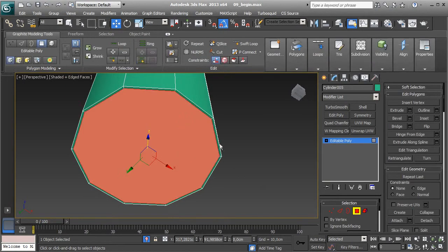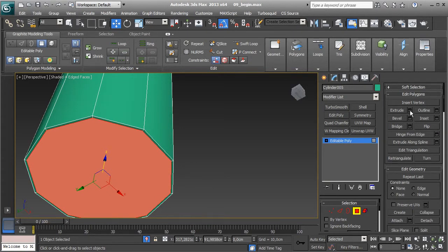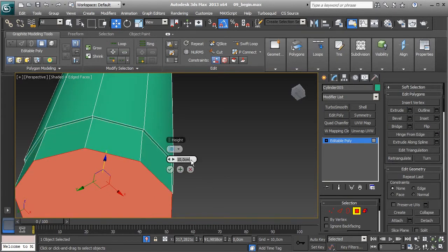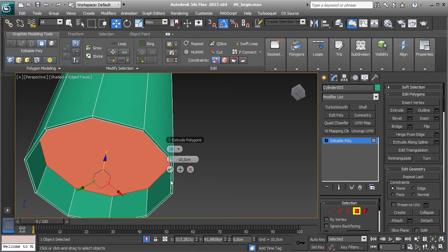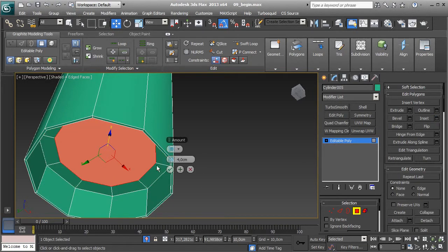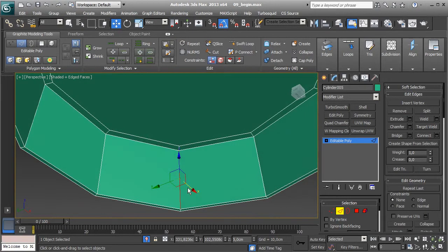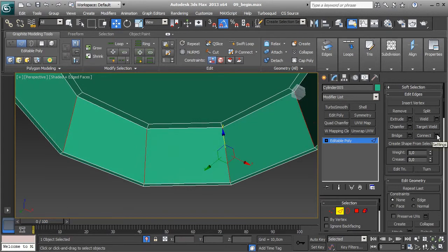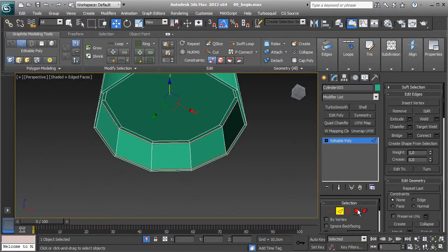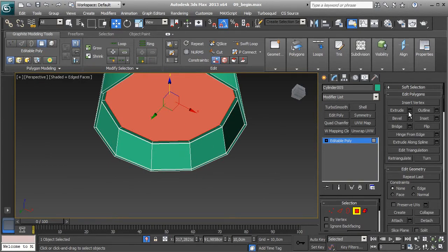Okay, now select this polygon and extrude that in by 10 centimeters. Hit OK, inset 1 centimeter and hit OK. Now select this ring by selecting this edge here and holding Shift. OK, connect two segments and pinch 95.